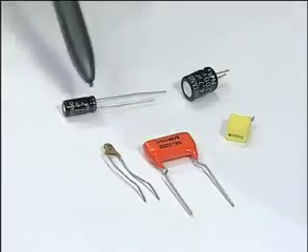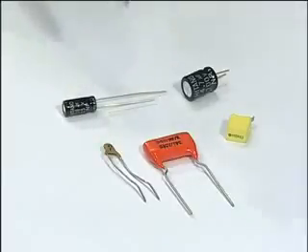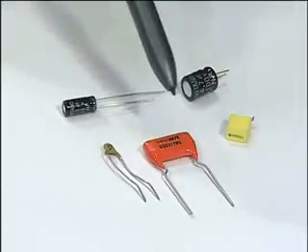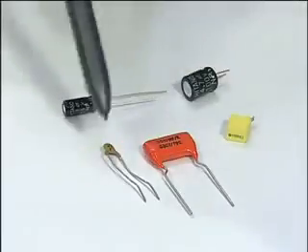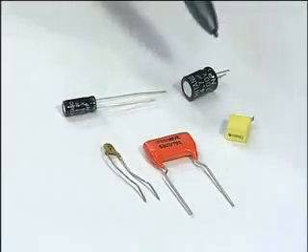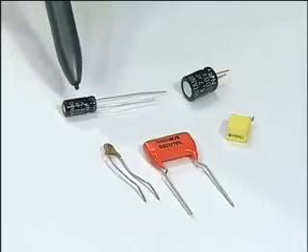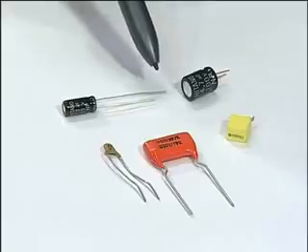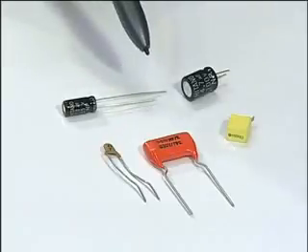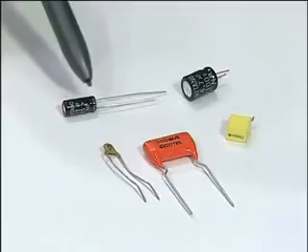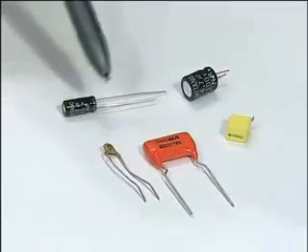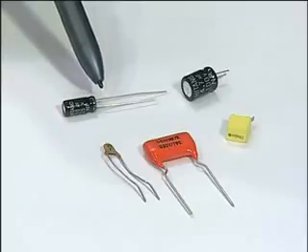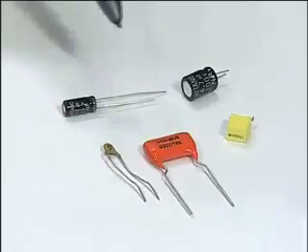So, these capacitors are in general used for holding the charges, whereas these capacitors also do the same function of holding the charges, but their application is more for frequency tuning, decoupling, things like that. So, this is aluminum electrolytic. You see there is one short lead and one long lead, that is to distinguish the positive and the negative pole. But even otherwise, on the body of the capacitor there will be a plus or a minus sign put near one of the terminals to distinguish it from the other pole.